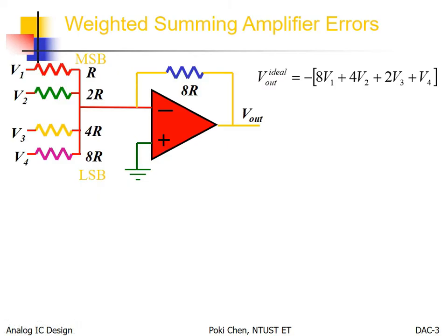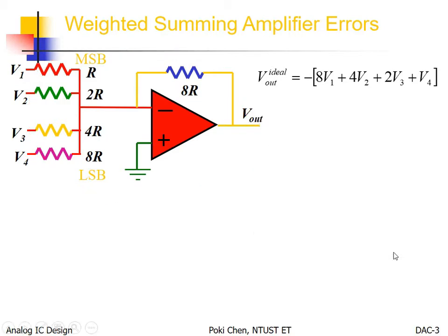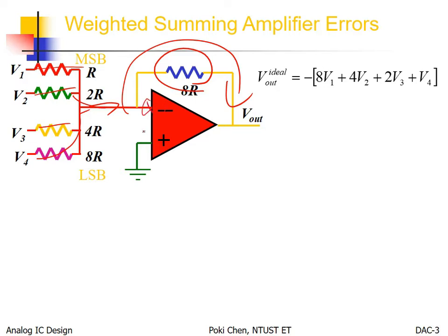Then allow me to show you what you already learned from microelectronics, but which can behave like a DAC. This is the summing amplifier. Ideally, according to KCL, Kirchhoff's current law, all the current that flows in needs to reach the output through the feedback resistor, because in theory the input resistance of the op-amp input terminals is infinite.